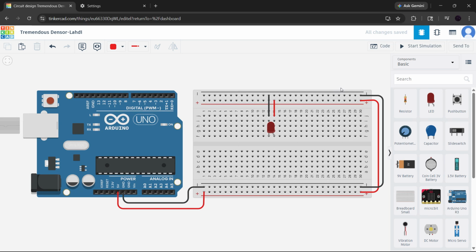Next, validate your component values. Check the resistor values in your circuit and make sure none of them are accidentally set to 0 ohms or an extreme value like 1 gigaohm. Values like that can break the simulation math and prevent the circuit from running correctly.